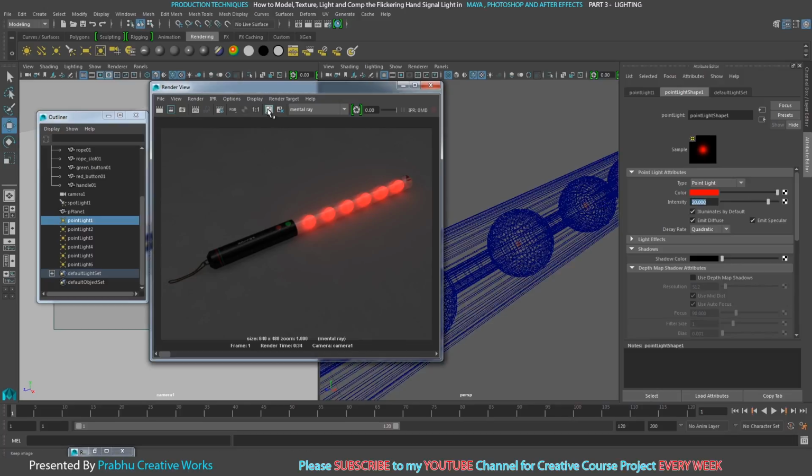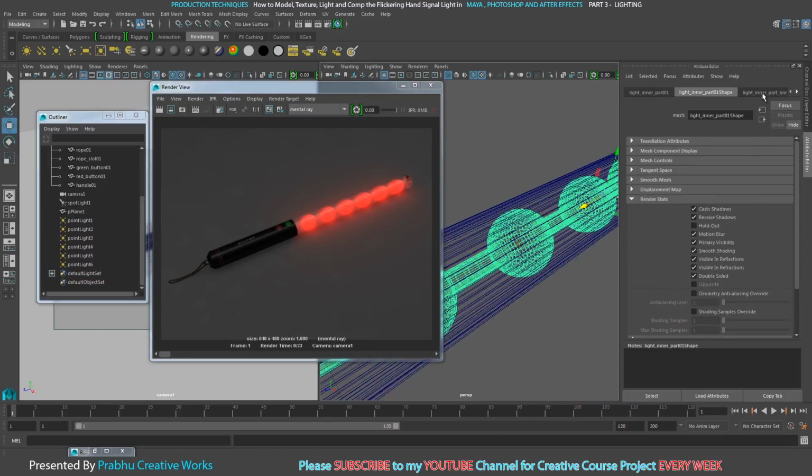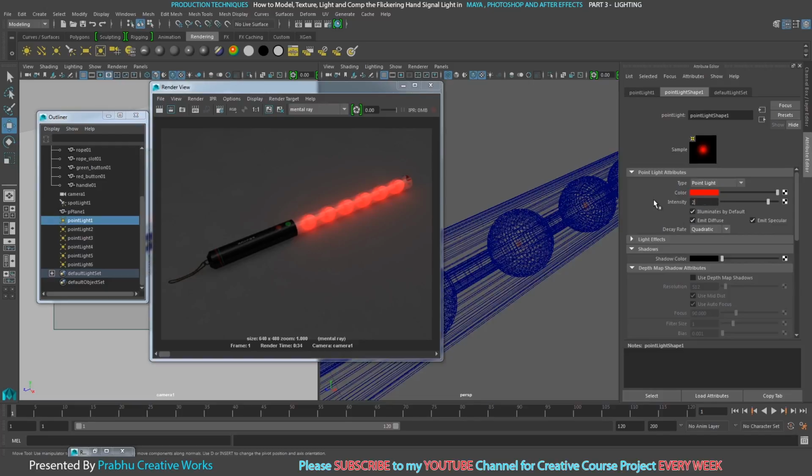So I will compare this one and click render again. I will select my inner object, and then reduce the transparency level a little bit. I will reduce the translucence a little bit. Okay, so I will click this one and render it again. I got closer, but I want more intensity for these point lights, so I will increase it up to 2.5. So select each and every point light and change my intensity.